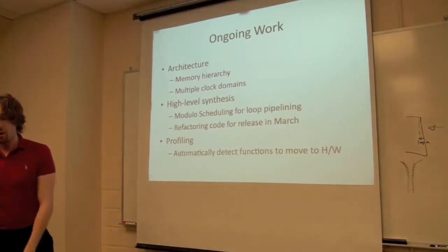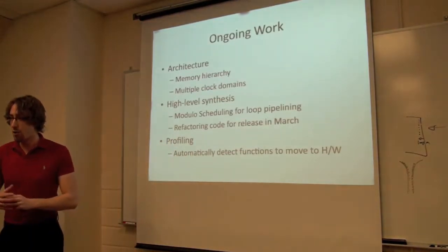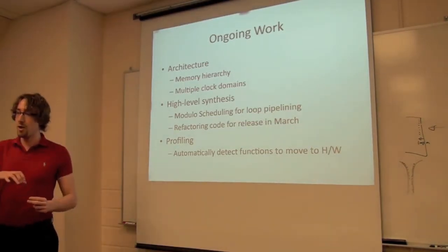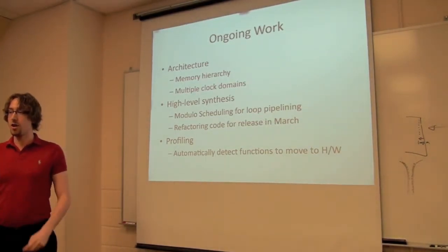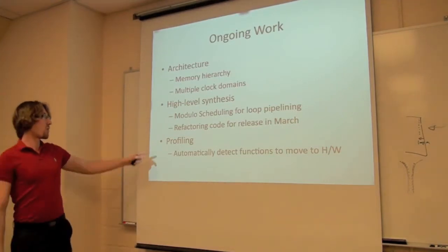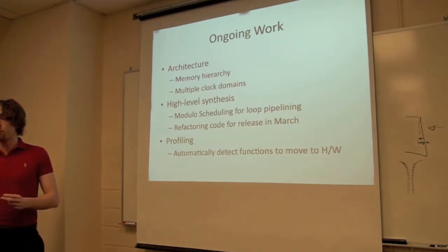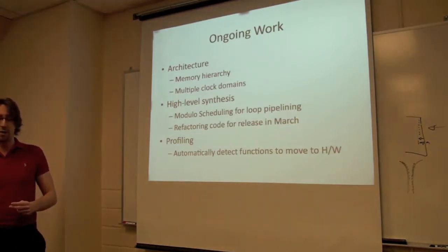So, just ongoing work in this project. We're looking into the overall system architecture, so the memory hierarchy, and maybe having multiple clock domains for each hardware accelerator. There's lots more work to do in the high-level synthesis portion. I really need to implement modulo scheduling for loop pipelining. I don't have any loop pipelining right now.